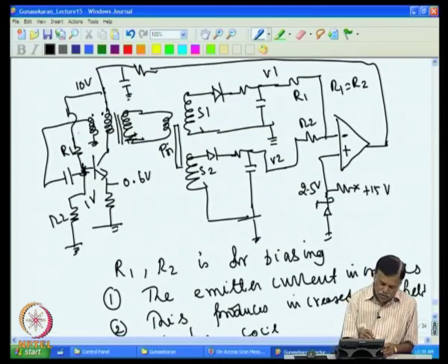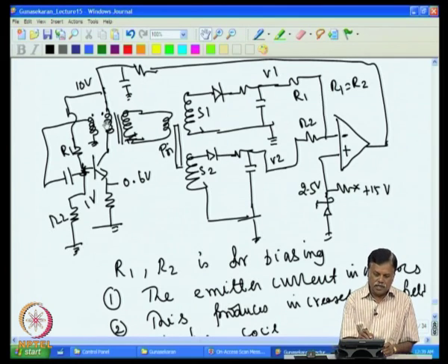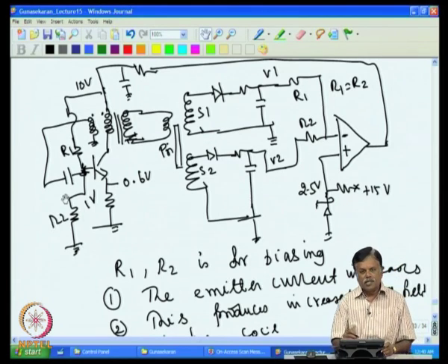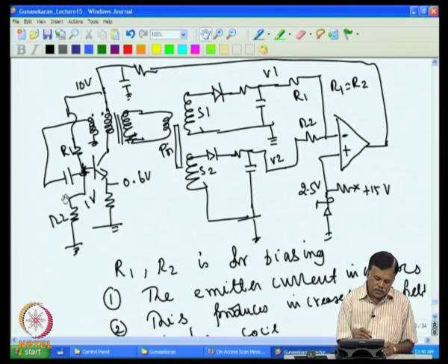So, first, as soon as you switch on, some voltage appears here, that increases the current through this, and that current flows through this. So, you have an increasing magnetic field, which increases the positive voltage here, that increases this voltage, and that increases the current further, which increases the magnetic field here, again more voltage comes, and then again current increases, more magnetic field, more increased voltage. Like that it keeps going one after another in a cyclic fashion. After some time you will find that this voltage has increased, and this current has also increased sufficiently, and no more increase in voltage is possible.